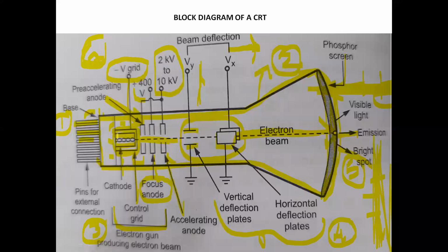Due to this, electrons are generated, and since they have little weight and no inertia, they move randomly around the cathode. In order to provide some control for these randomly moving electrons, a control grid is provided on the cathode and negative voltage is applied to that grid.